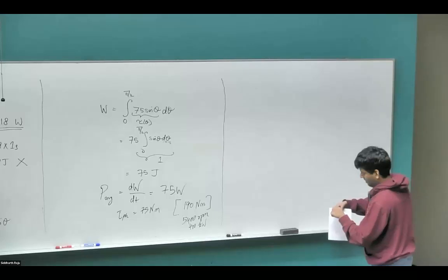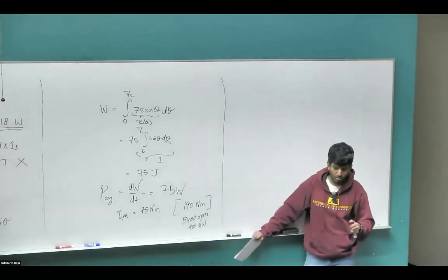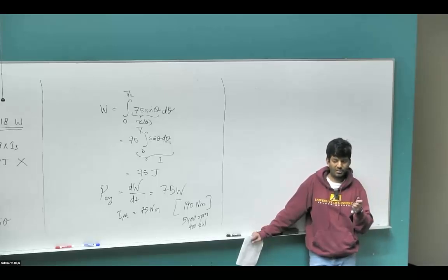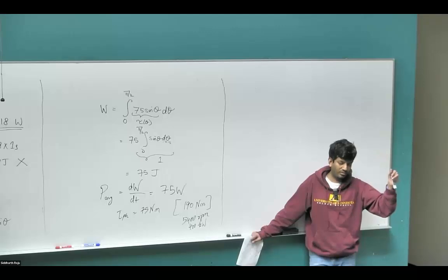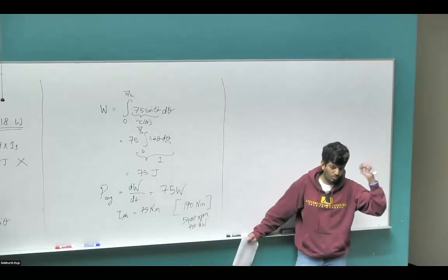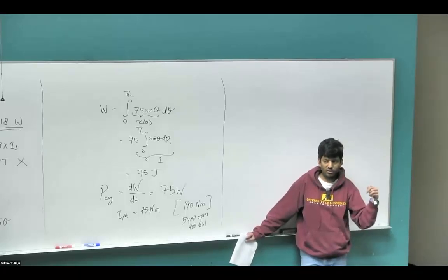When we looked at the energy in the total rotor inertia, there was a sufficient amount of energy, half J omega squared. So in a traditional power system, you have the synchronous generator, not permanent magnet though, the rotor would be excited separately, but the functional principle is pretty much the same. The generator keeps spinning at some speed, and then let's say suddenly an industry turns on their whole load, or a residential complex turns on their whole load, where is the additional energy going to come from?